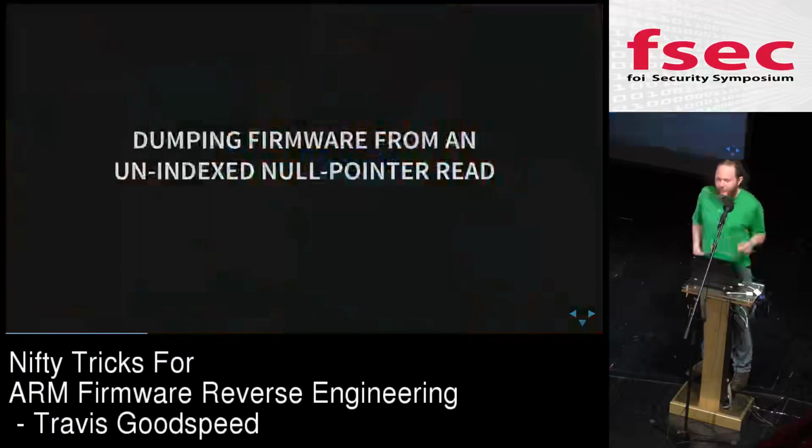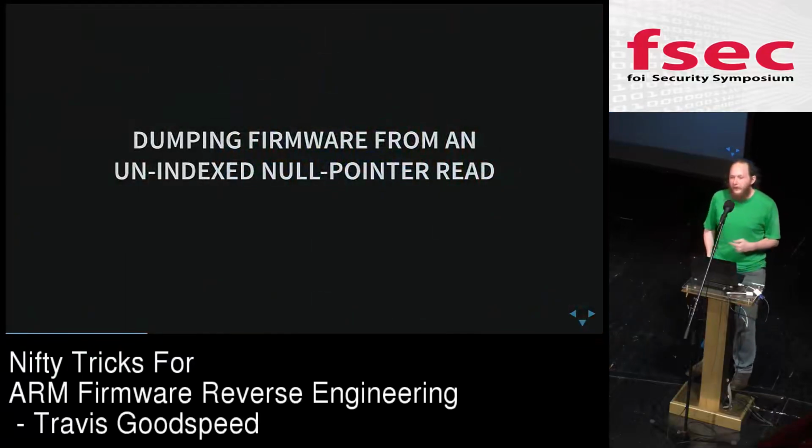But in order to do that, I first had to get a copy of the firmware out of the radio. When you are reverse engineering malware or anything running on a PC, you have the advantage that you have very good debuggers, and you also have the electronic file that you can read. So you see the .exe file, you know that if you start it, it will do something to begin the malware, and you have an easy starting point for reverse engineering. You might fight with a packer, but at some point it will be in RAM and running from RAM, and you'll have a copy of it.